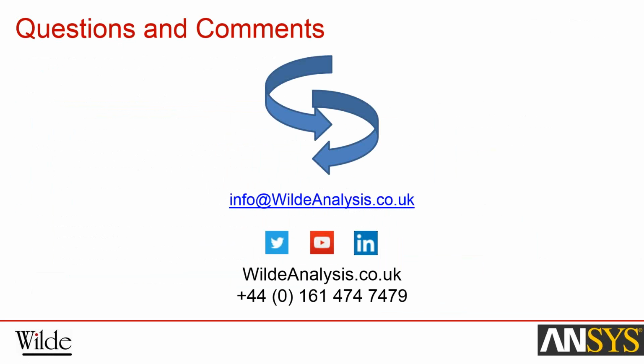Okay, I've got another one. Is it possible to use porous baffles in CFX as opposed to having...? Yes, absolutely. And we can talk about that offline if you want. We use baffles, porous baffles all the time to model grills and other types of equipment. So it doesn't have to be a subdomain. It could be even a porous sheet if you wanted, based on specified area fraction.